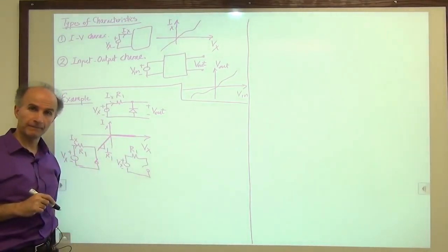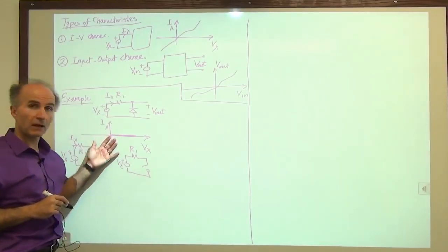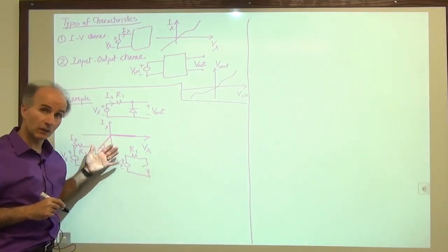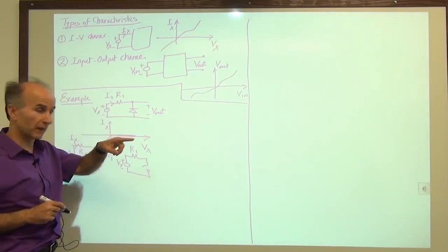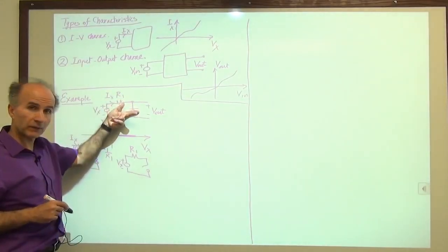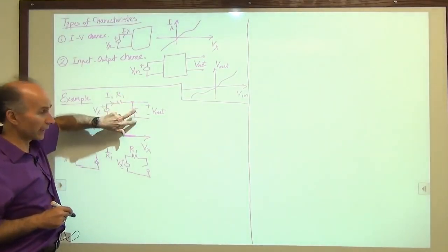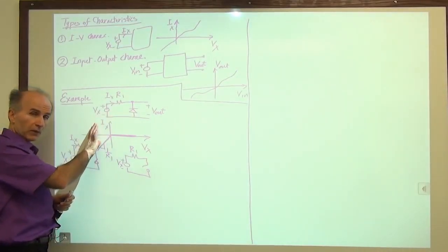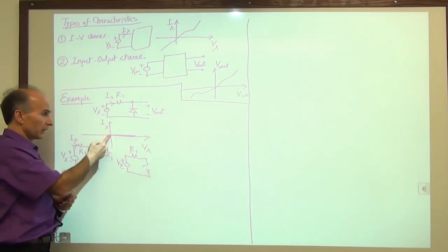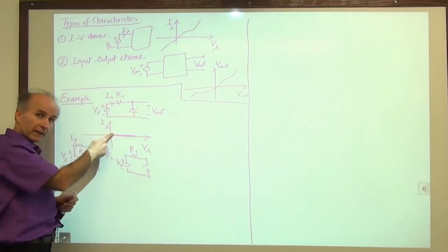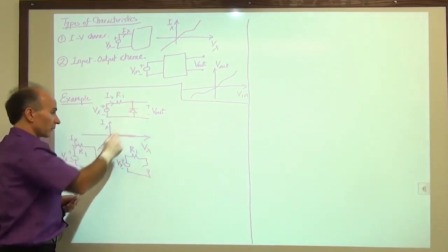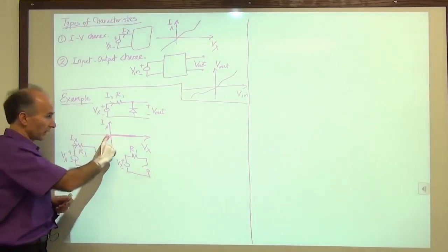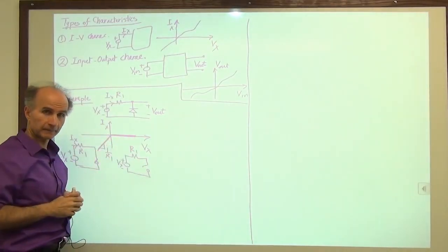That was simple. You see that this behavior is complementary or similar to what we saw previously when the diode was the other way around. So by flipping this diode downward, I managed to flip this characteristic also this way. We used to have 0 current here and a proportional current on this side. By flipping the diode, we have a proportional current here and then 0 current on this side.